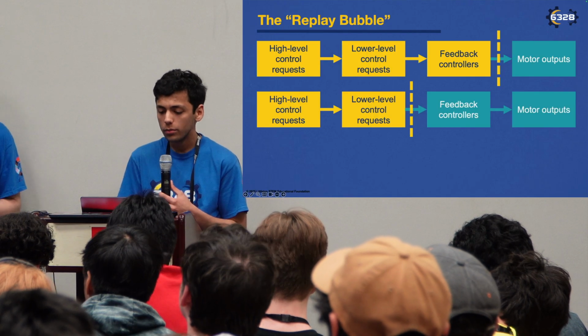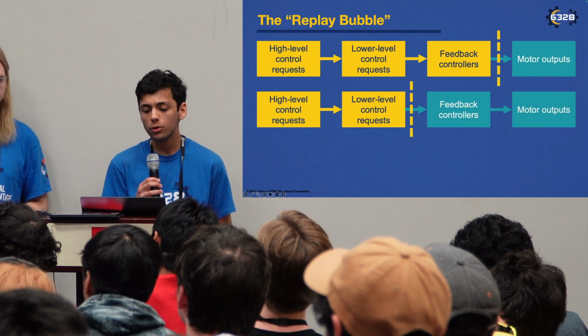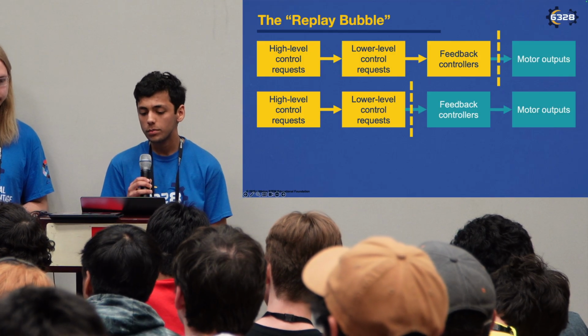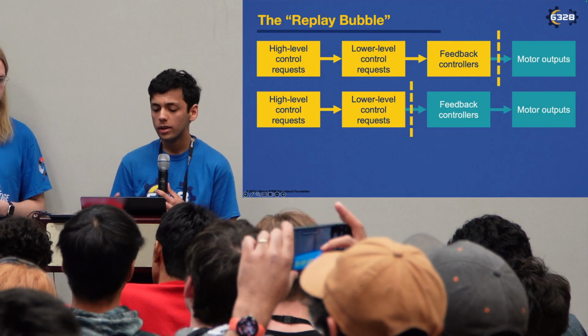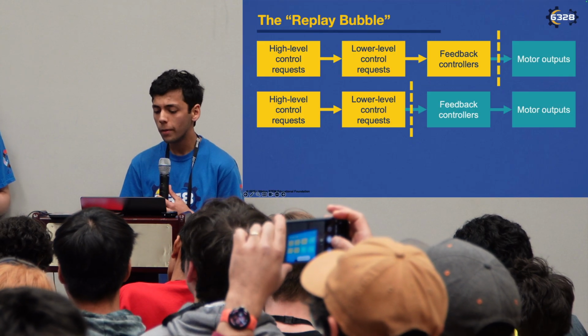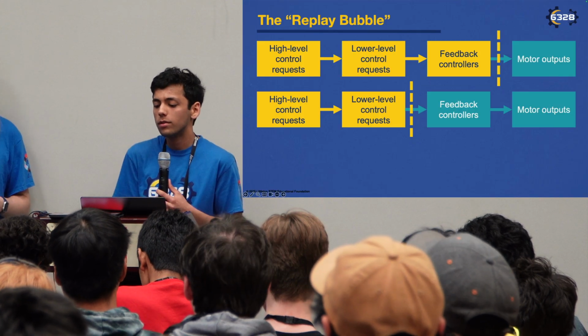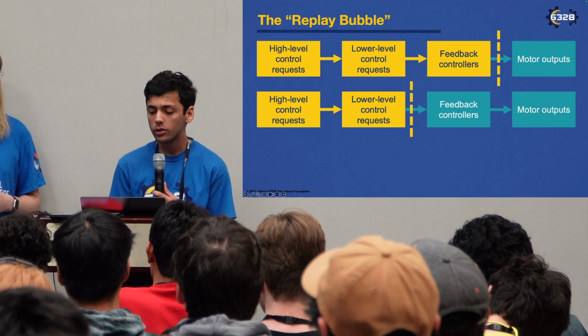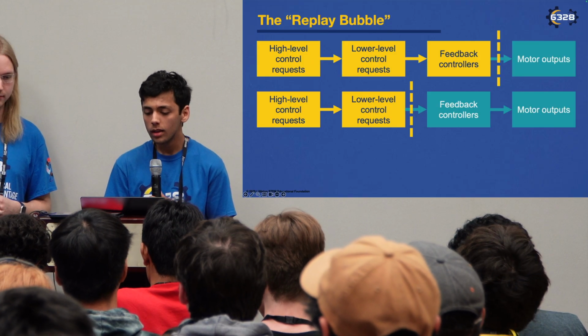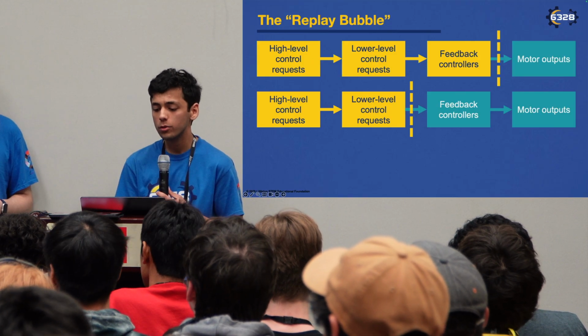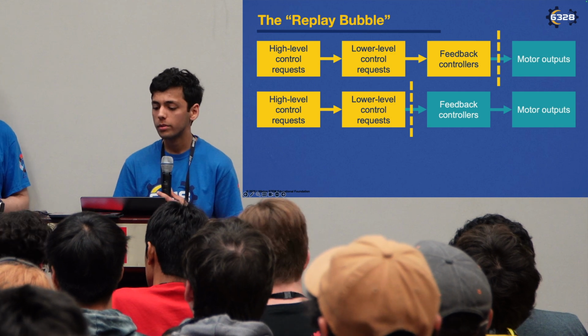Another common option is that we have the PID controllers run on a smart motor controller, and all kinematics happen within the subsystem. There's also some nuance here. If you're using a profile, you might have to decide whether to run it on the Rio or on the controller. You might have also noticed that our first case study with an elevator profile only works when you're running a trapezoidal profile on the RoboRIO. And the structure takes advantage of faster feedback loops, also allowing a lot of the logic to be replayed.